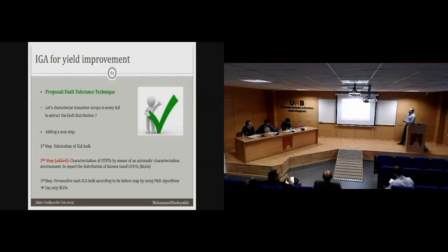But when it comes to drop configurable structures, the printer is going to do a very simple job of just leaving some drops, very normal drops, not very tiny, 40 or 50 micron in diameter. So I think both the design and the printer equipment are collaborating to have more promising results compared to the previous style.